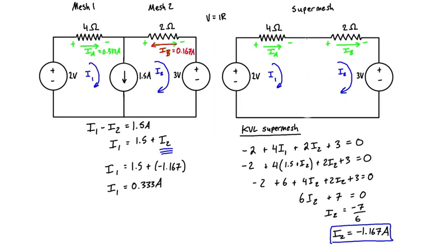So you can either write it going to the right with a negative current, but that's kind of confusing, so I would recommend just switching the direction if you're drawing it on the diagram, or just writing it down below with an arrow. You know, like we're just saying that IA is equal to 0.333 amps to the right, and IB is equal to 0.167 amps to the left.